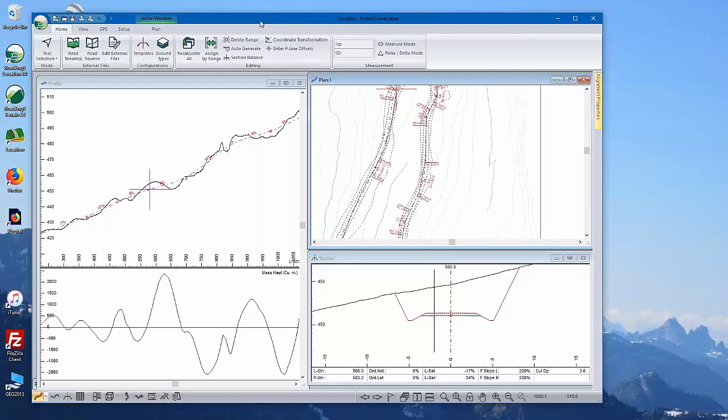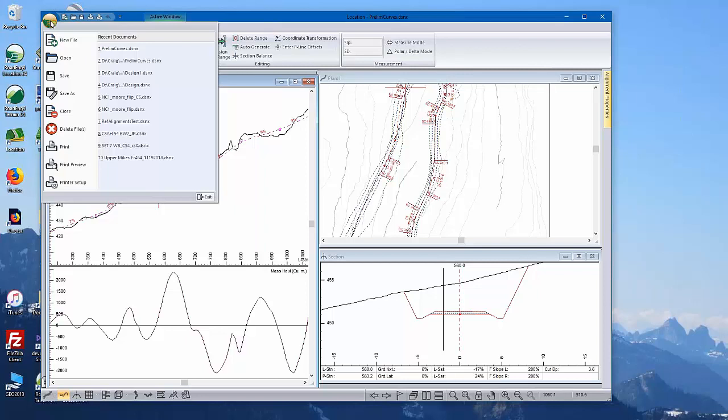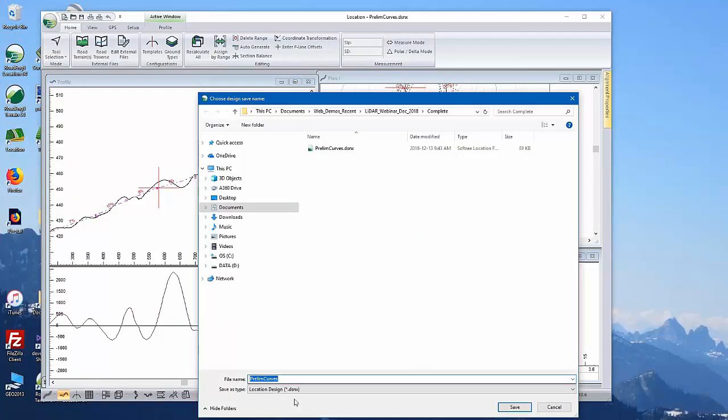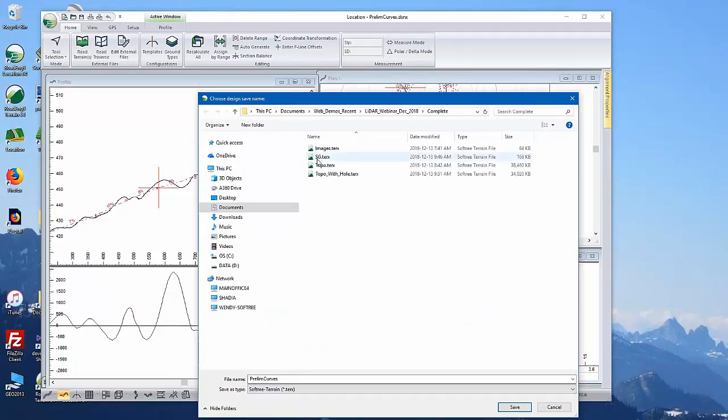So now I want to put it back into the original surface. So I go up here and I save this file and I choose a terrain format, TerX format, version 8 terrain format. I did this already, I'm going to call this subgrade 1.